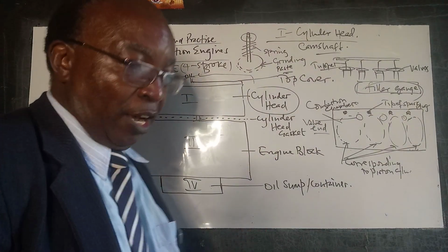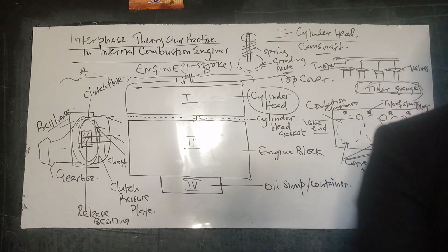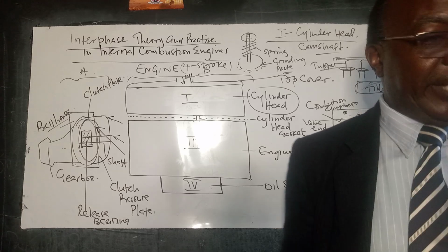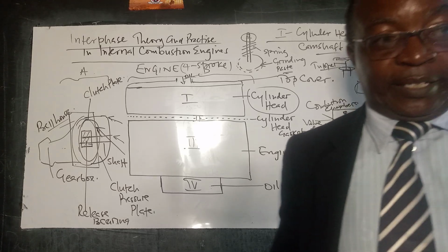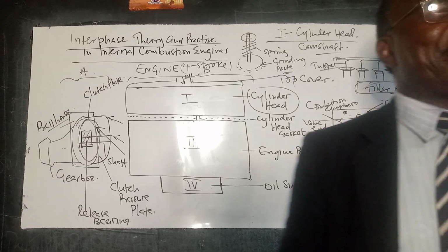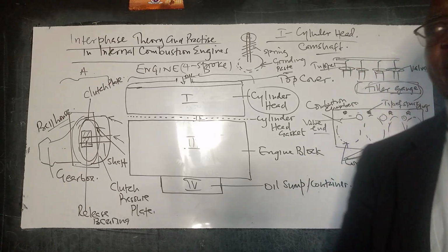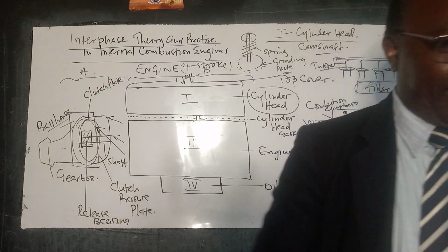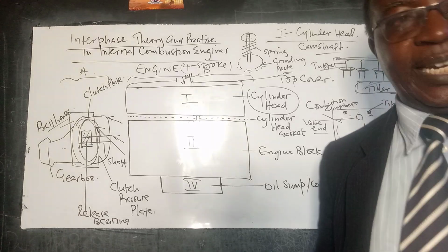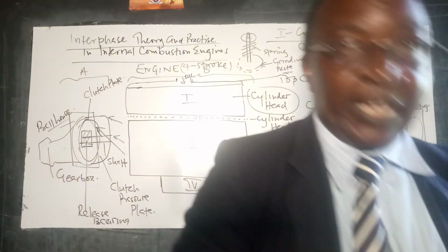And of course, you want to do it with the valve sitting on the cylinder head, so that it's perfectly fit and there's no leakage. In fact, sometimes you test it by pouring a liquid to see if it actually goes through. There should be absolutely no leakage. Remember the idealized assumption we talked of in terms of the piston: perfectly fitting, rigid, frictionless, and massless. Some of those, frictionless and massless, are not practical, but that's the ideal, but it should be perfectly fitting. So even the valve should sit properly.